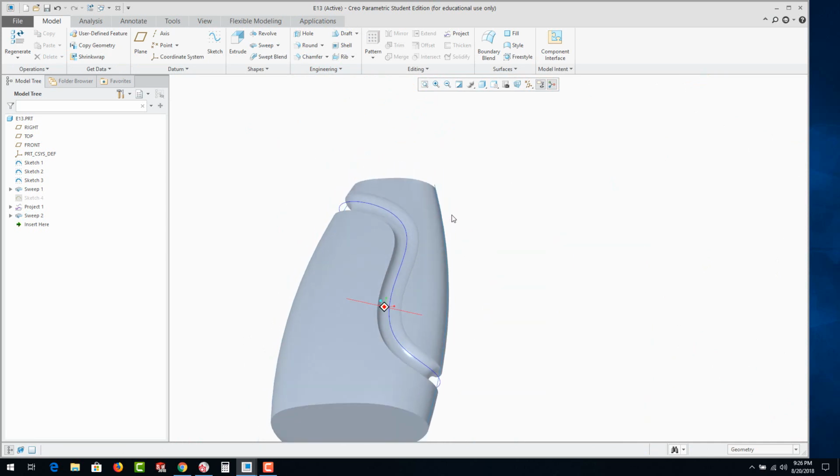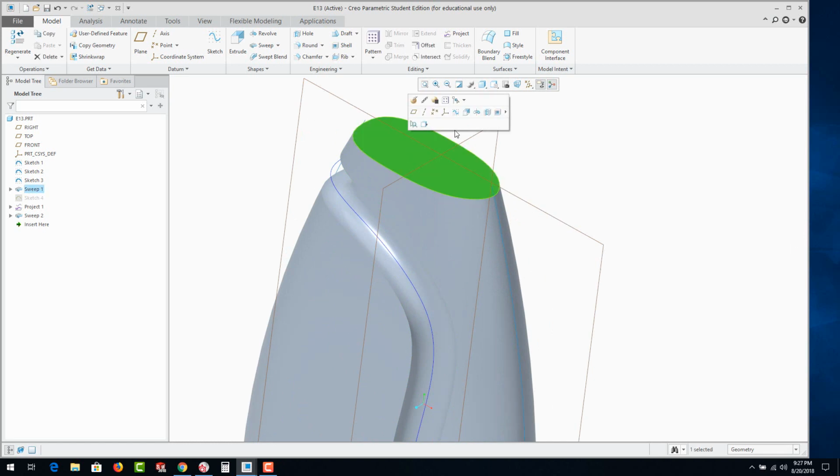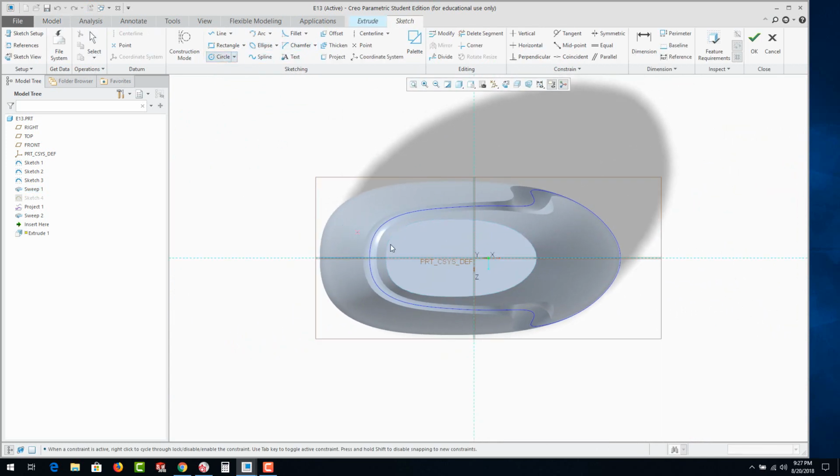Now we're going to put a neck on the bottle. So go ahead and select this top face here. Go to the Extrude button and draw a profile. Again, since we're using our own dimensions here, just draw it enough to where it's not touching the edges, but a little bit of a distance away. Mine's like 1.2, that's pretty good. We could go ahead and just 1.25 there. It might be too large for yours, so feel free to adjust it.